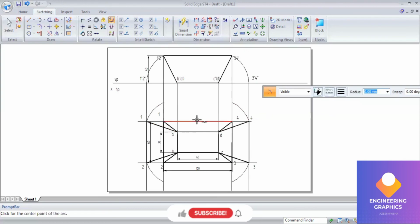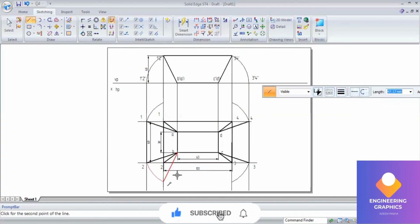Now you join it with the straight lines here. So the newly cut arc points, we get it, right. So connect it with those A, B, C, D points. Go to line and then connect it with the vertical edges, and that is the development of that particular lateral side. See there, like this you can join.